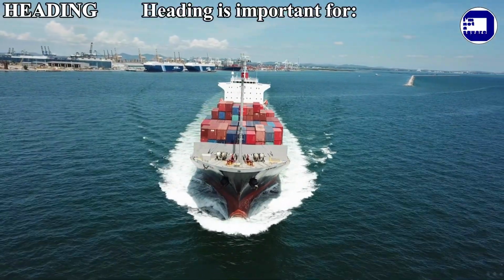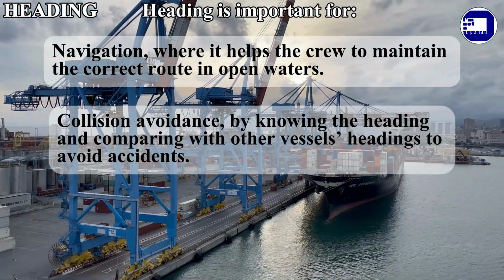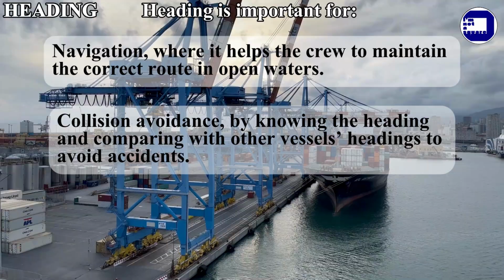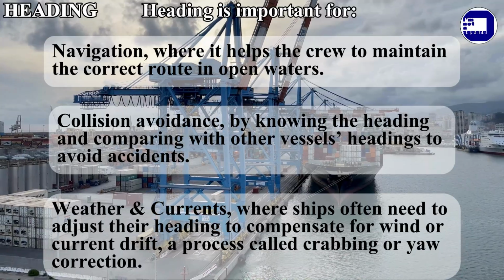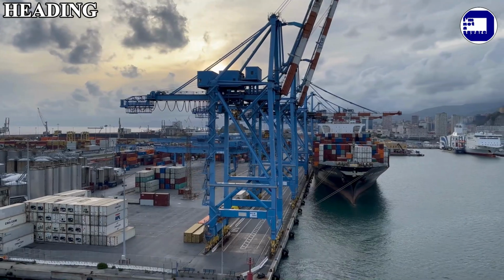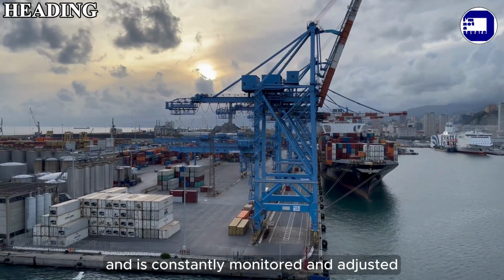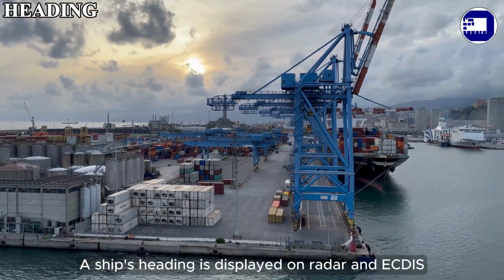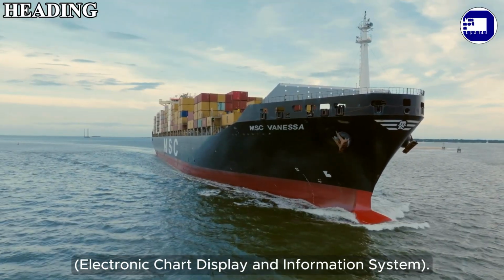Heading is important for navigation, where it helps the crew to maintain the correct route in open waters. Collision avoidance, by knowing the heading and comparing with other vessels' headings to avoid accidents. Weather and currents, where ships often need to adjust their heading to compensate for wind or current drift, a process called crabbing or yaw correction. Heading is measured using a gyro compass or magnetic compass and is constantly monitored and adjusted by the ship's autopilot or helmsman. A ship's heading is displayed on radar and ECDIS, Electronic Chart Display and Information System.